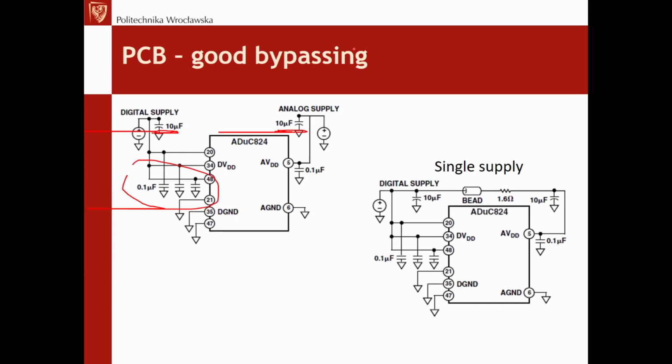Then close to each input, we shall have the so-called decoupling capacitors. The decoupling capacitors are used as very low impedance sources, especially for high frequency operations. Therefore, in order to avoid the inductance of the lines, the decoupling capacitors, which filter out the high frequency noises, shall be as close as possible to the power supply pins of the microcontroller, for example.